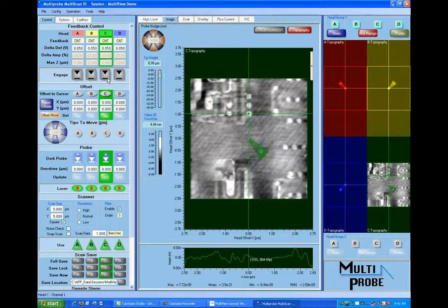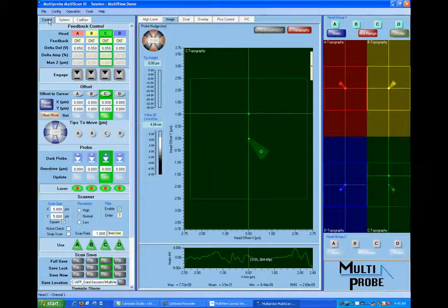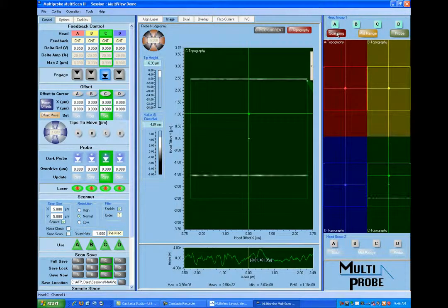Mid-range, disengage our probes, and now we'll move on to our last point. This will go over along this same metal line here. The goal of this 3-point alignment is to choose 3 points that are not collinear. Basically, this means that they're in an L shape, and this allows us to take into account the sample rotation as well as any scaling vertically or horizontally.